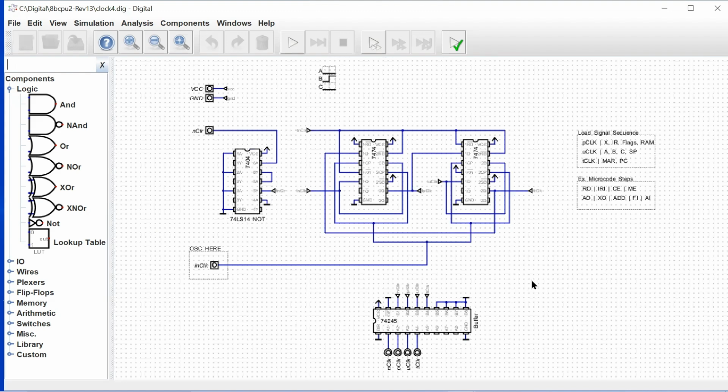So I eliminated all of that circuitry that we had, which was like four additional logic chips that, when the run signal went low, monitored for the clock to get to the not clock state before the clock would stop.